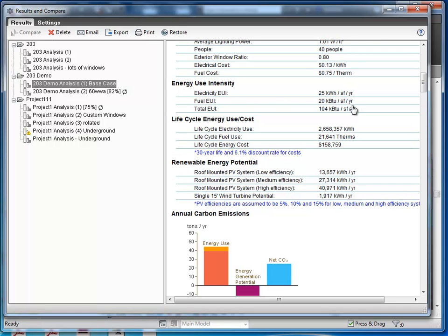But yes? If it's underground, and the sun isn't hitting it, how do you show that? So if it's underground, you just move the building below level 1. Okay? And I've actually played around with it, and it does reduce the load, but not as much as I thought it should. So if you're doing that, maybe you can email me and let me know, because I can take a look and see if the numbers are about right. But what you do is you just move it below the level 1 ground level.